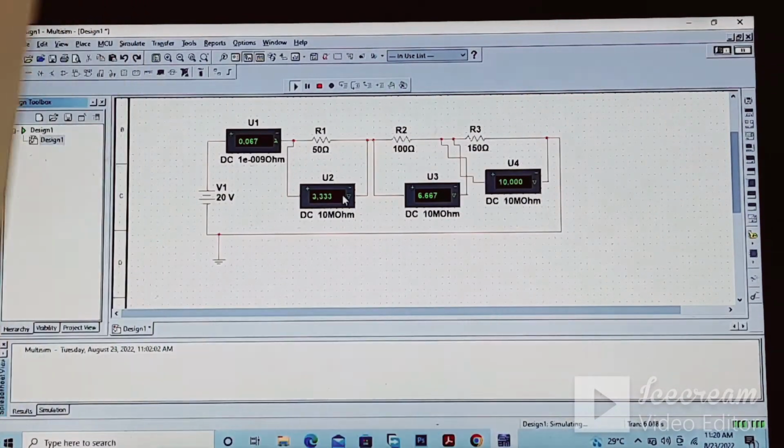By applying Ohm's law, V is equal to IR. So I is this total current, which is multiplied with this R1, and this will give us the reading of the voltage V1. And here we can also calculate this voltage through the mathematical formula according to Ohm's law, V is equal to IR. So V2 you can easily find by multiplying the total current with R2, and also you can find this voltage V3 by applying Ohm's law, multiplying the total current IT with this R3 resistor.